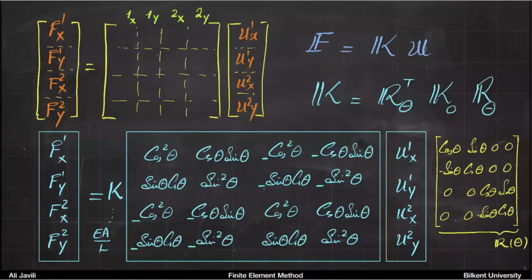And then if you know the stiffness for the flat element, so that is your K0, the one which is just, let's say, K, minus K, minus K, K. That's easy. So if you take that and you multiply it by this rotation matrix and its transpose accordingly, you get this.